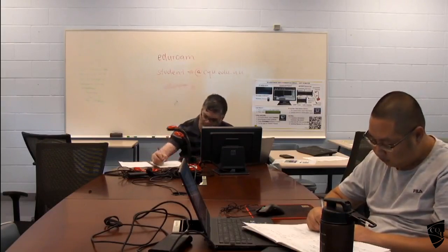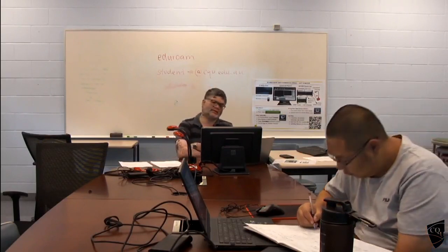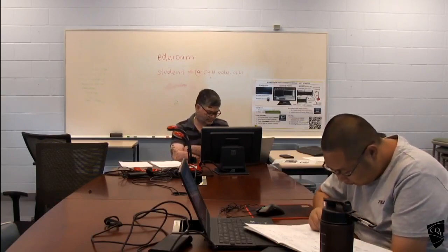Where that number comes from, AS 1170 part 0. Okay, short term and long term factors are given in AS 1170 part 0. There are tables, depending on the purpose of the building, the purpose of the member. You should be able to find out the W values.